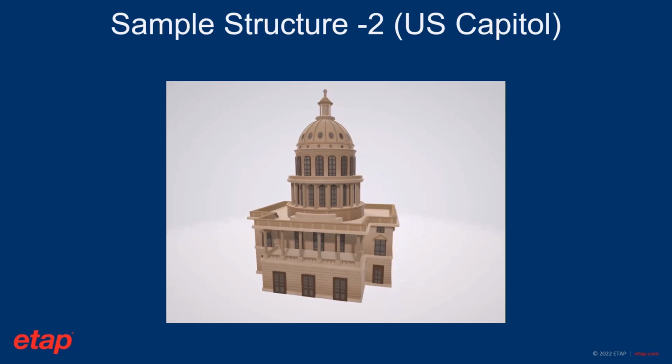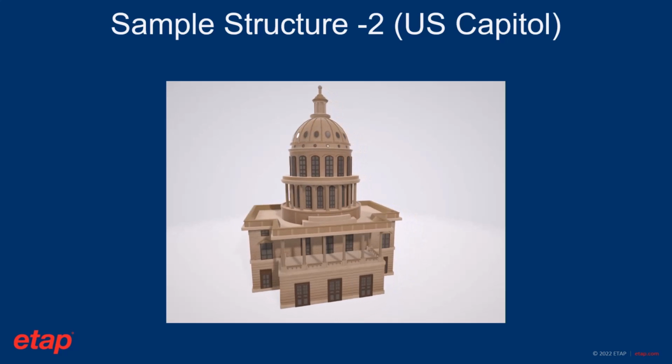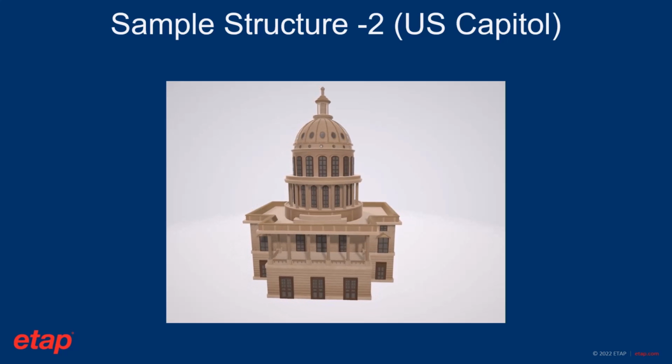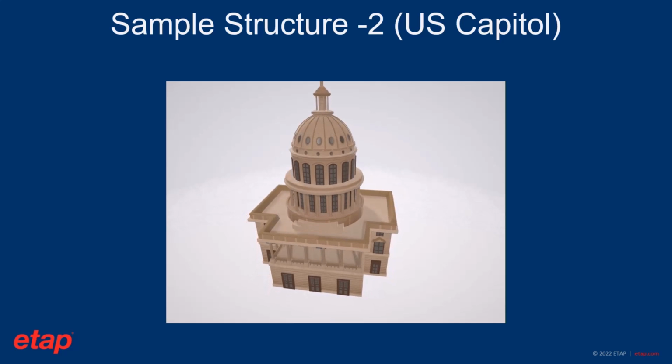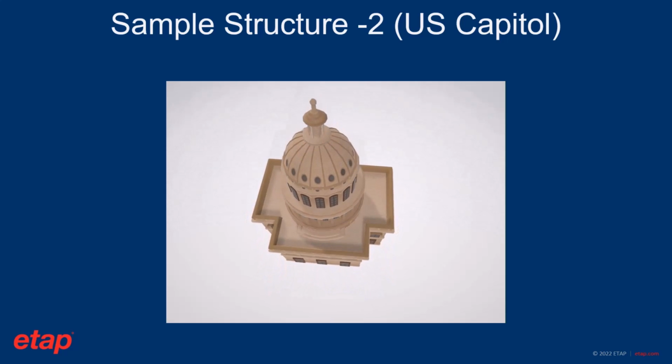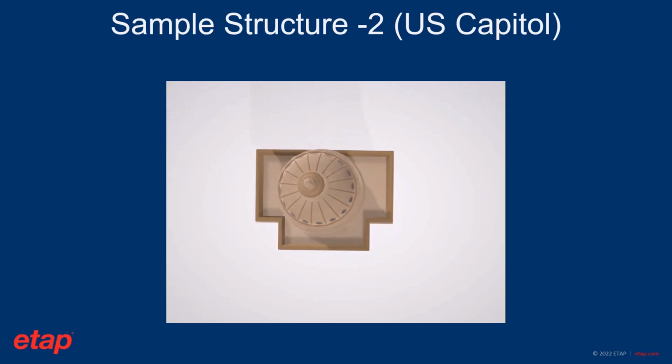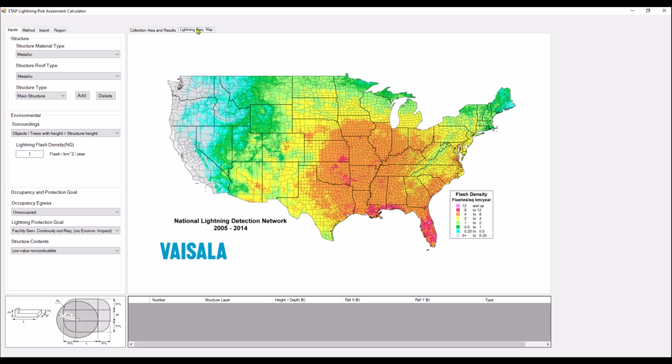created in the lightning risk calculator by getting the plan view of this particular structure. First of all, once we determine the irregular shape of the plan view and the complexity that this building involves, we first identify the location basically. So the location of this one could be brought into the calculator, which is somewhere in the Washington, D.C. area, at 8 flashes.